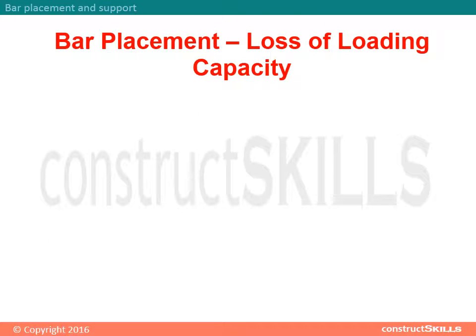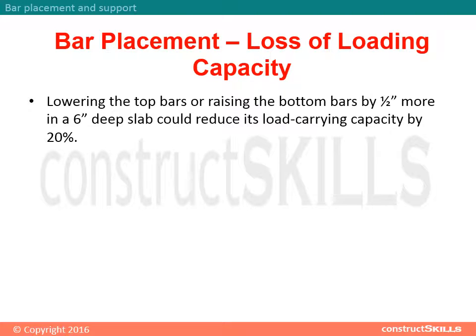Loss of loading capacity of bar placement. Lowering the top bars or raising the bottom bars by half an inch more in a 6 inches deep slab could reduce its load carrying capacity by 20%.